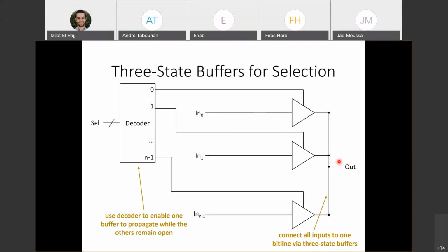So now we've solved the problem of the OR gate and the AND gates, but we still have a very large decoder. In practice, we break down the SRAM into multiple smaller SRAMs, and then select the result from these different SRAMs. So it's as if we broke down our decoder into multiple decoding stages. We're not going to get into that in this course, but that is a very good observation: we still have a very large decoder, and we solve that problem by breaking the decoder into multiple stages.